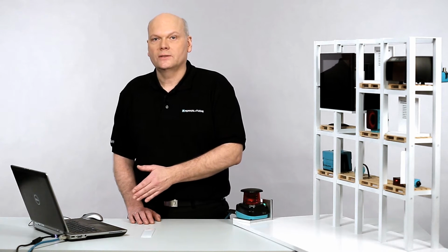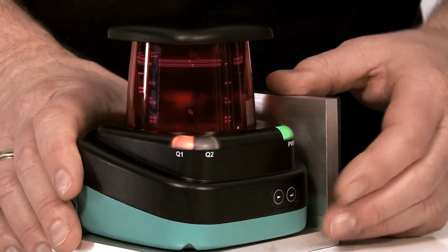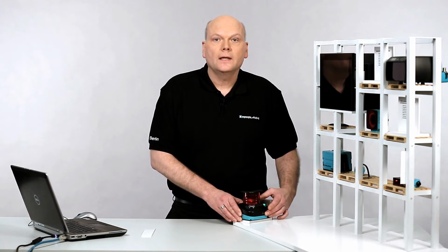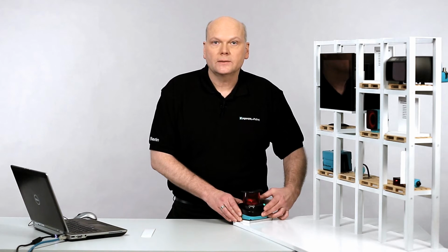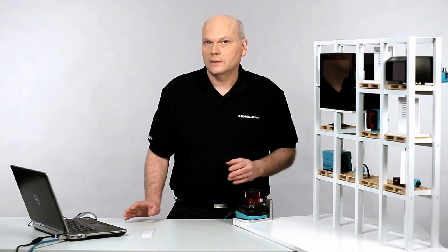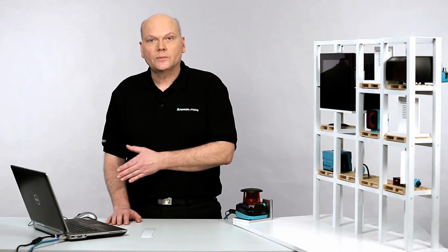To demonstrate the easy setup, this test environment will show you how to interact with the R2000 and the DTM configuration software. The R2000 provides an Ethernet interface for setup and configuration with software. The R2000 menu options will assist you with setting and determining the applicable Ethernet parameters. Using the push buttons on the front side of the scanner, you can access the Ethernet parameters, and also configure the PC Ethernet interface accordingly. After that, connect the R2000 to the computer.